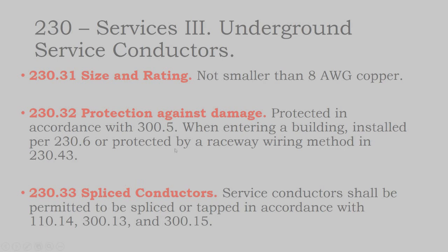We have services, a callout being not smaller than number 8. Then we get protection from damage, where entering a building, they need to be protected in a raceway. Spliced conductors.